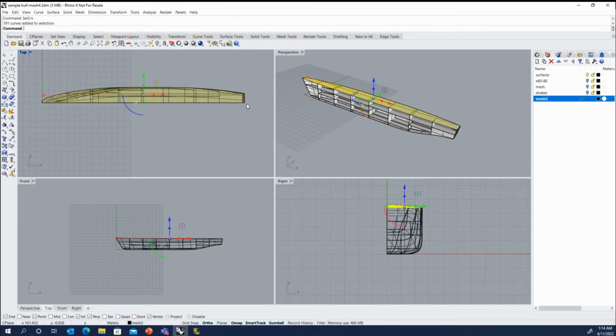If I were to split one of those curves and rejoin it or do some other destructive operation, it'll be considered a new object. So it'll get out of order from all of the others. So that's one thing to be aware of. When you run this script, you may want to do it right after you use the contour command to create all these things.